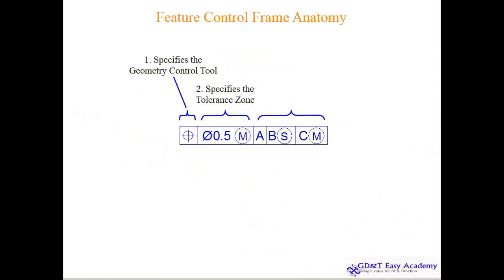If the diameter is 10 and because of manufacturing we get 11, that is the MMC. But in case of a hole, the MMC is the smallest size of the hole. That means if because of our scenario we get 9, that 9 is the MMC. MMC is basically when the part weighs more. If you go to the weighing machine and weigh that, it will be maximum. So in case of a hole, the smaller the hole, the more material. So it weighs more. In case of a shaft, the larger the diameter, the more it will weigh. That means when you leave more material, that is MMC.